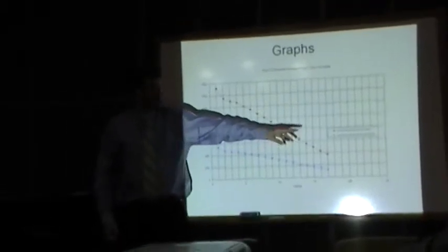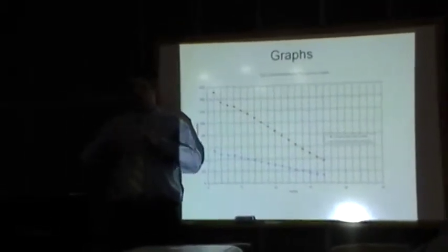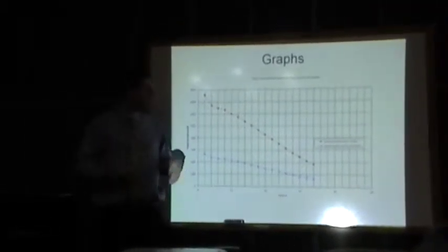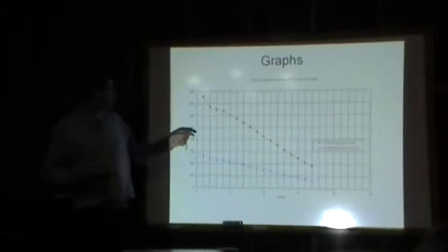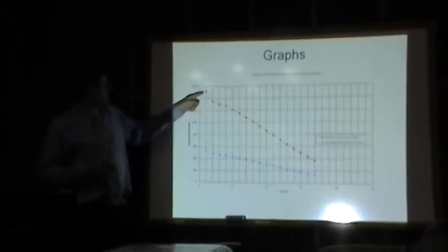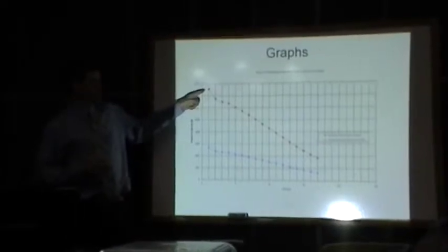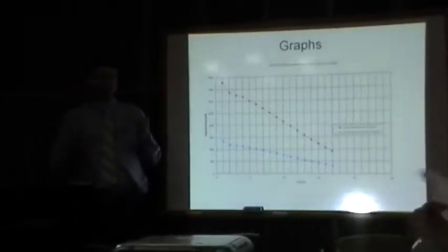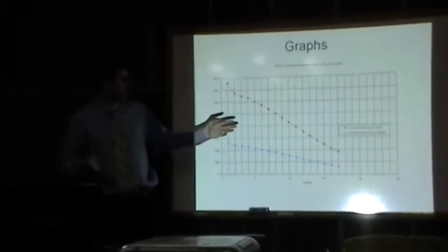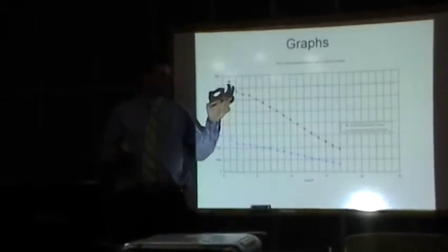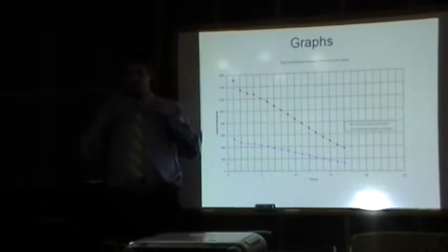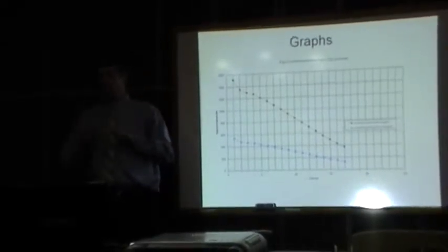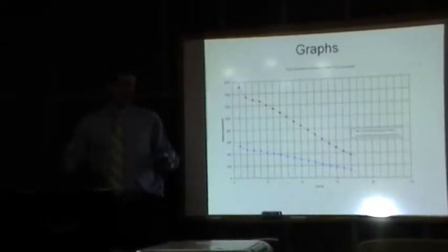Whereas if you could modify the core so that it flows nicely into a nozzle and accelerate to about Mach 2, you can get about 1500 newtons, which translates to about 142 seconds of specific impulse. The only reason why that number is important is because that was the goal of what they wanted to accomplish using the heating of the CO2 and then blasting off.